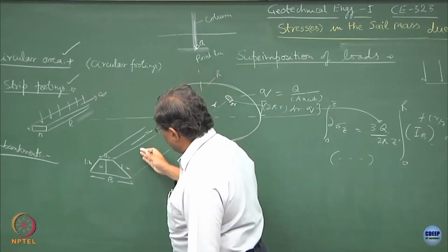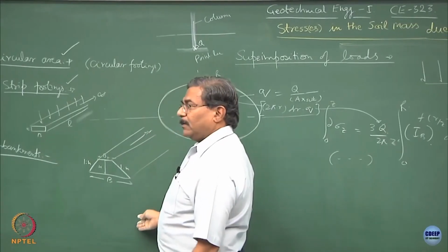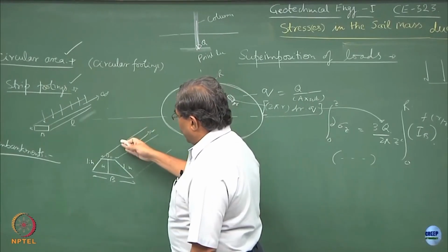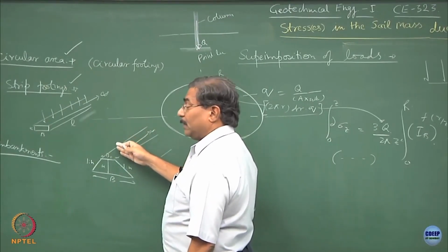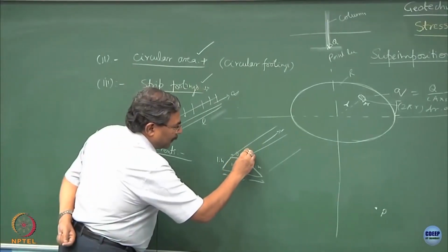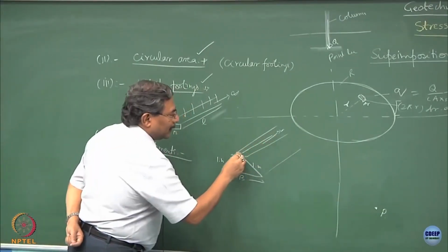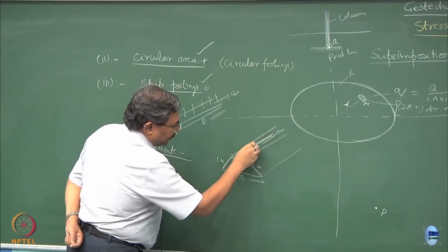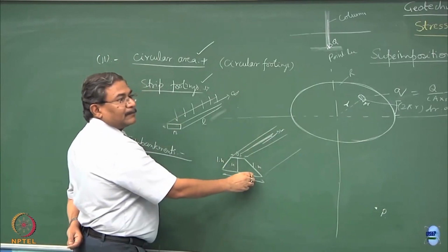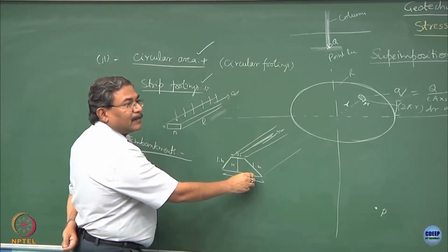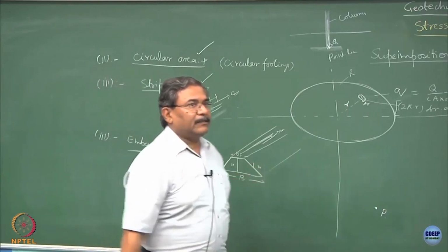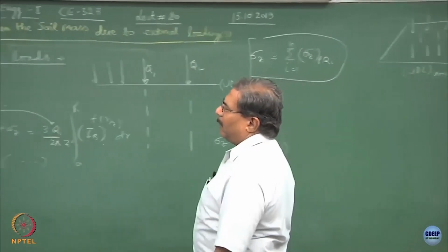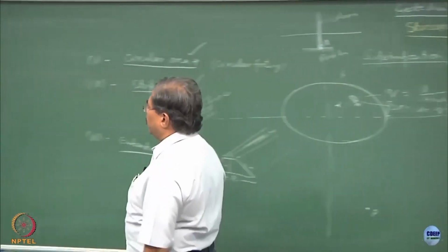So suppose I ask you to find out what is the state of stress at the bottom point, no problem, you can still model it. The entire loading can be, now there is a trick. The load is going to act over here, the railways are going to run over here, the roadways are here, okay, aircraft loading is here. We have to delegate this stress at the base of the embankment. Clear? I used the word delegation. A better word for this is dispersion of the loading.